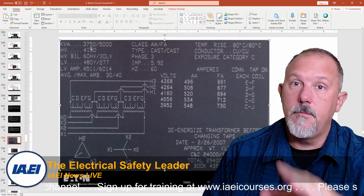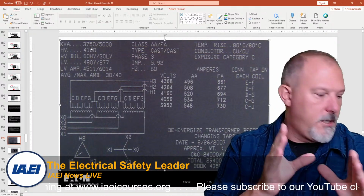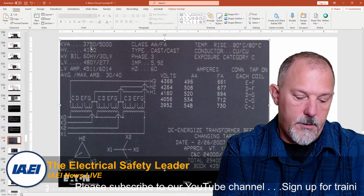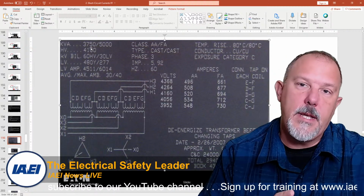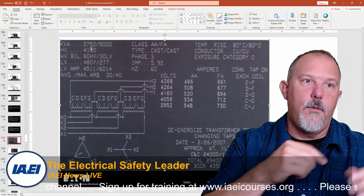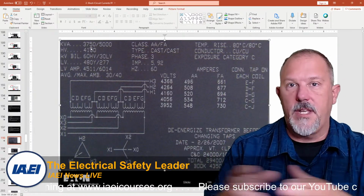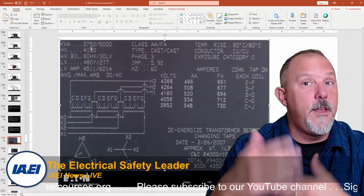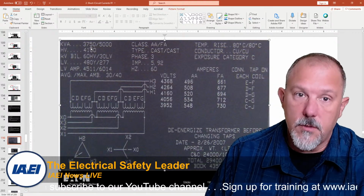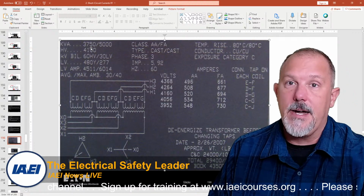Now, what do we do for the impedance of a motor? We have different impedance values depending upon the duration of the fault current, whether it be the first cycle or longer. So we will change the impedance of the motor based upon how many cycles of current, because we know that is a changing impedance.